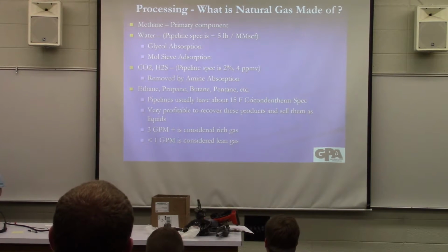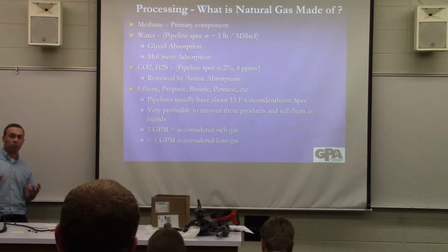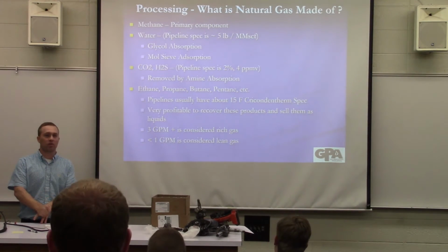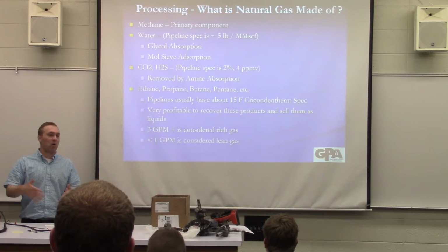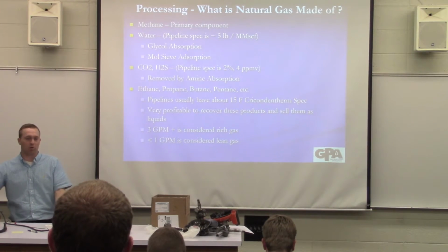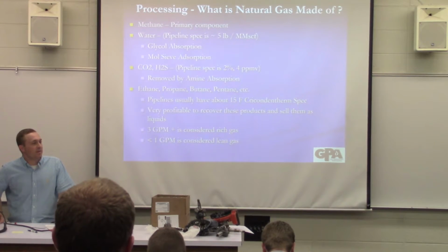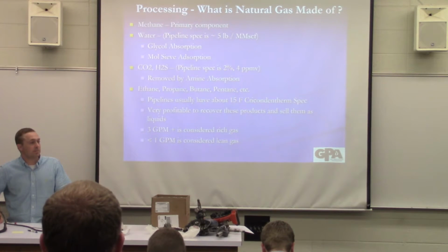And then the ethanes and propanes, those hydrocarbons, we recover for 2 main reasons. The first one is to meet pipeline specifications. Why do you think they have pipeline specifications? They don't want too rich of gas, or too high of BTU content, or too much propane or butane. Why would it be bad to have too much of it? Well, it seems like you would optimize your turbine operation, your combustion system, for a specific fuel composition.